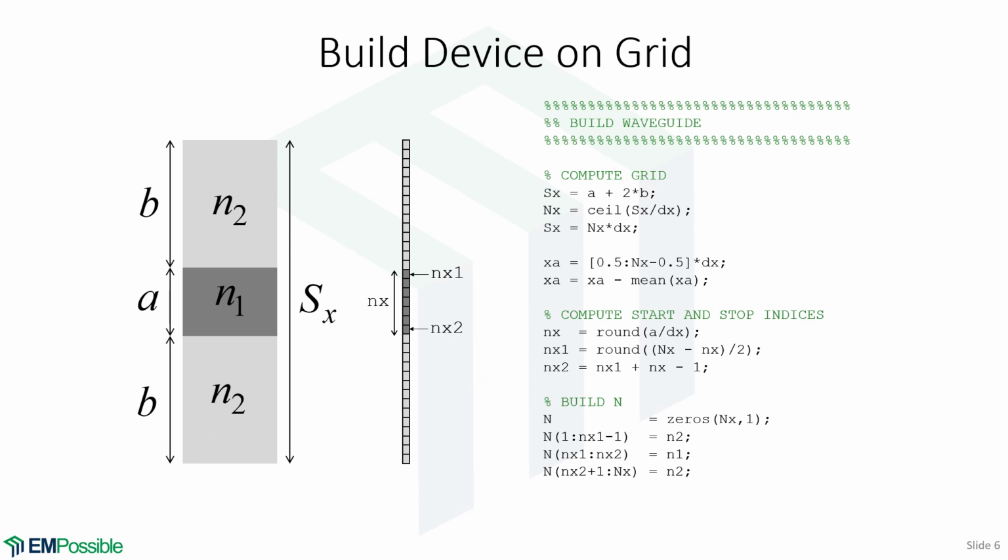So here's how that works. And we're going to center this. So I also call this my centering algorithm. So first we calculate a little nx. This will be the number of cells wide this A region is. So that's what little nx is representing. So I take the physical size and I divide by the cell size. Now this might come out to be a fractional number like 17.2. Well, we can't have 0.2 of a cell, so I'll round that. So we are making the closest possible guess as to the number of cells wide the core is.